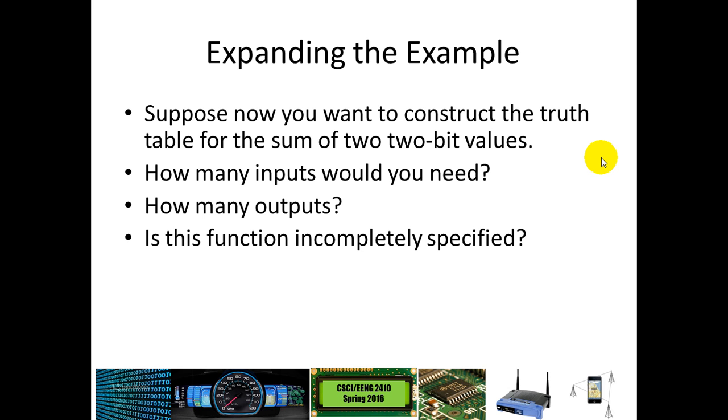And then the question is, is this function incompletely specified? Well, it does have a possibility for every possible input, but with a 3-bit output, it is not possible to achieve an output of 7 if our logic is defining that. So if we had that driving another circuit later on, then that 7 would be a don't care. So on our output, it's just never possible to achieve 7. So it's not truly incompletely specified because we do have a deterministic solution for every possible sum, but one particular output value is unreachable.